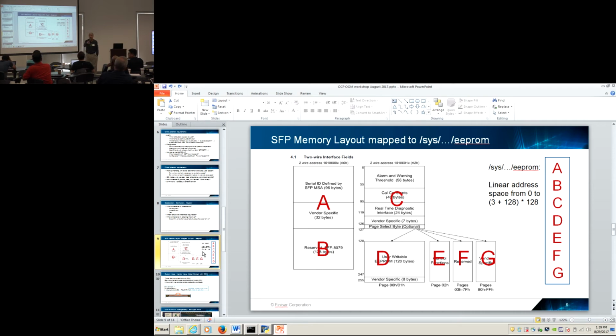Okay. So I have one suggestion that says just go ahead and implement all 16K plus bytes, and if the user tries to access a page and the device itself doesn't support it, you just get an error back. Or you get zeros. But the spec actually says for SFP you get zeros back. Is that okay? Are we comfortable with that? It's always full size and you just get back zeros? I'm fine with that. That's easy, and as the EEPROM guy, that's what I expect. I know what I'm after, and if it doesn't come back, well, I'll handle it.